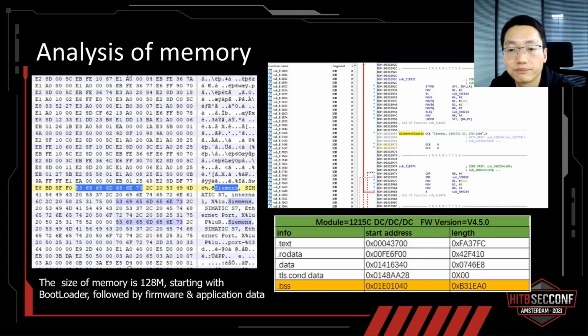We analyzed the latest firmware version of S7-1215C in detail, May 2021, and obtained its code segment, read-only data segment, and the starting address and length of the data segment. The corresponding decompiled pseudo code is also obtained by loading the code segment content using IDA.